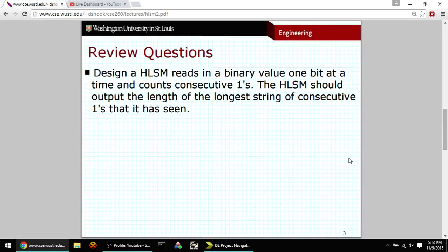However, this is going to be 0 at first, and as soon as we get here, it should now be 1, right? Yeah. So I was checking it every time it transitions back to the count state and back to the wait state. Every time current run is incremented, I check if current run is greater than longest run, and if so, then longest run gets it. Yeah. I think it only needs to happen here and here. I don't think it needs to happen here. I'm not sure that it will hurt anything. I think it's just extra. Does that make sense? Yes. It only needs to happen here and here.